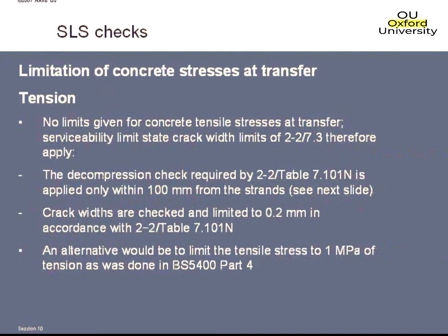In terms of tension at transfer, there isn't actually any specific provision in the Eurocode. Whilst BS 5400 used to say you could have a tensile stress of 1 megapascal during transfer, there isn't anything at all as a limit. As a pragmatic approach, you could use 1 megapascal of tension, because we know that works from the past, and since it doesn't say anything about it. Or arguably, we should just follow the normal rules on crack widths and decompression. So depending on the environment, we either need to check decompression under the just forces at transfer, or we need to check crack widths. It's a lot simpler just to actually check transfer to 1 megapascal like we used to do, to be honest.